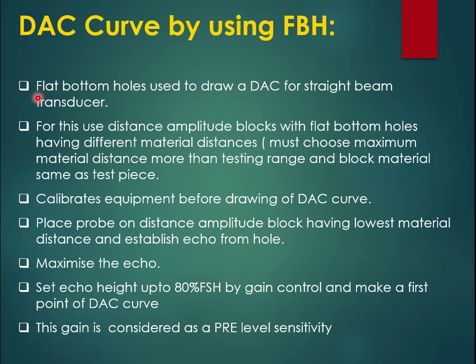First, flat bottom holes are used to draw the distance amplitude correction curve for straight beam transducers. Considering the transducer types, we generally have two types based on how the sound travels in the material. If the sound travels straight, we consider them straight beam transducers.